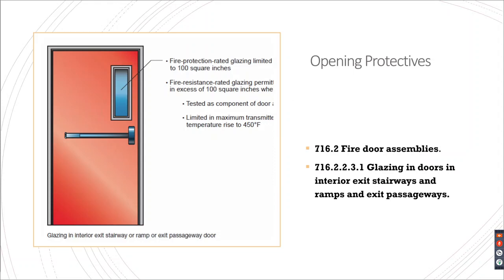Just a visual for you. So it limits the glazing to 100 square inches in the exit enclosure doors. If it exceeds that, you've got additional testing that has to occur.